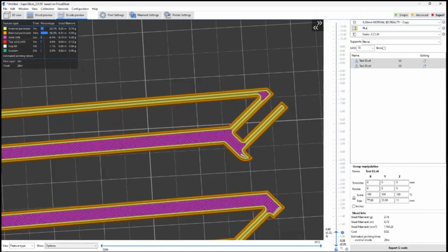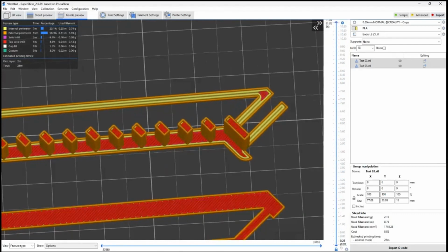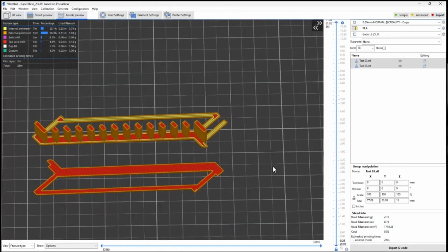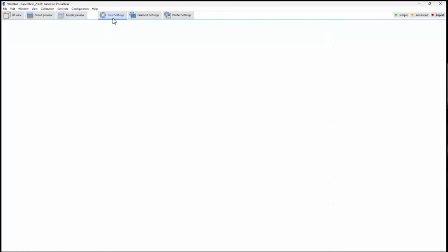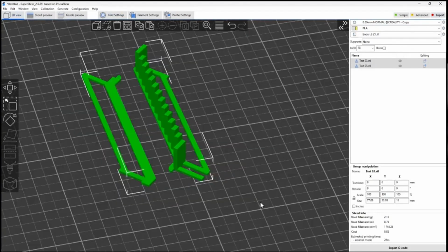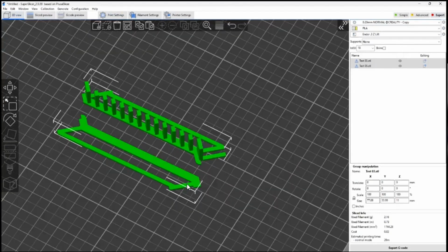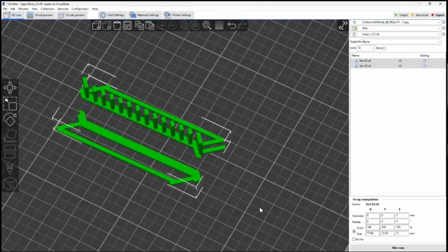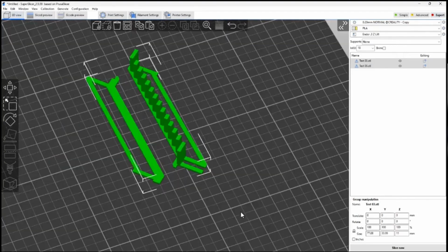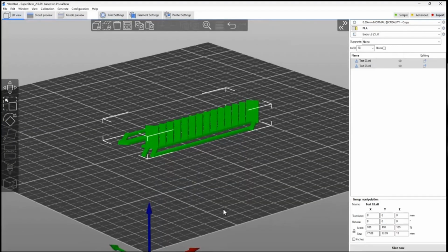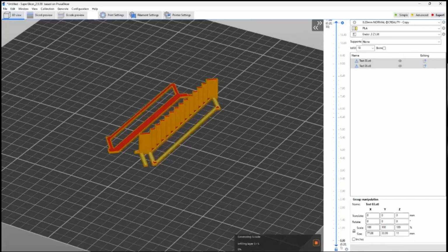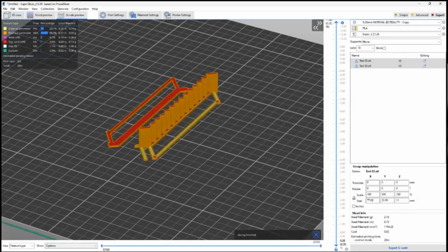Would you print that as one file, Eddie? Yeah, just put them next to each other. Oh. Yeah, that'll just print easy. Chuck something else on there as well, or do a couple of them at the same time. But yeah, what's the time on that slice? Because it is quite, well, there you go, 28 minutes. That's a 0.2 layer height.